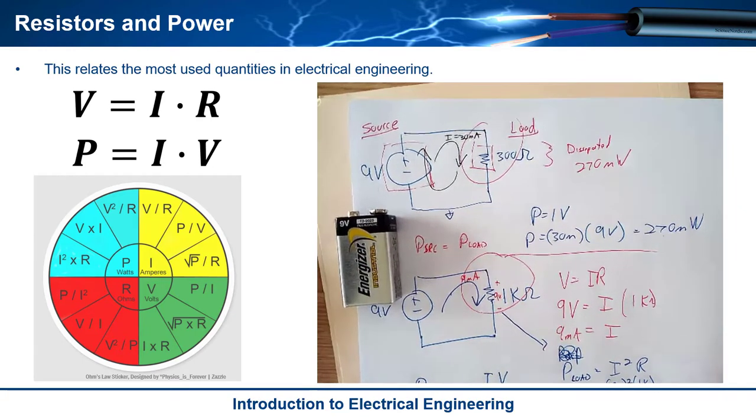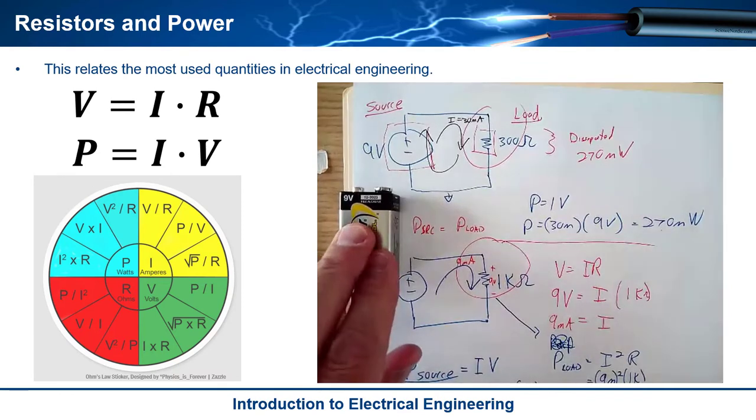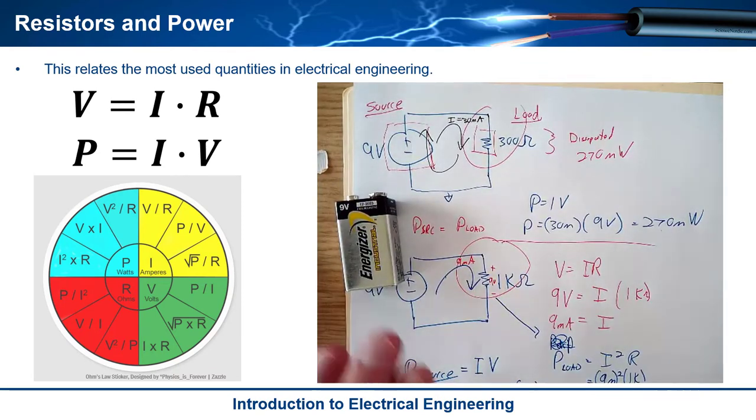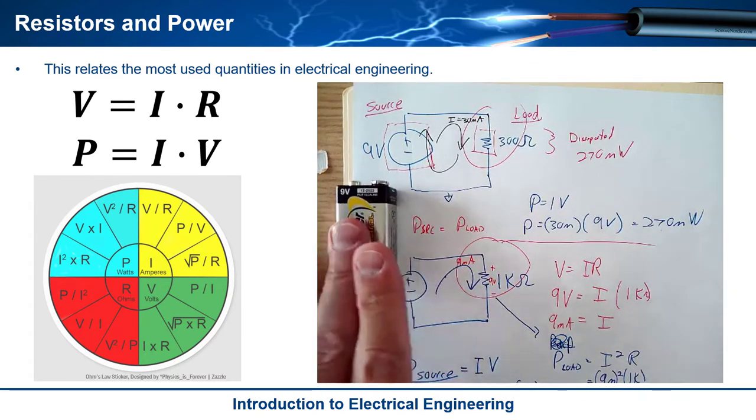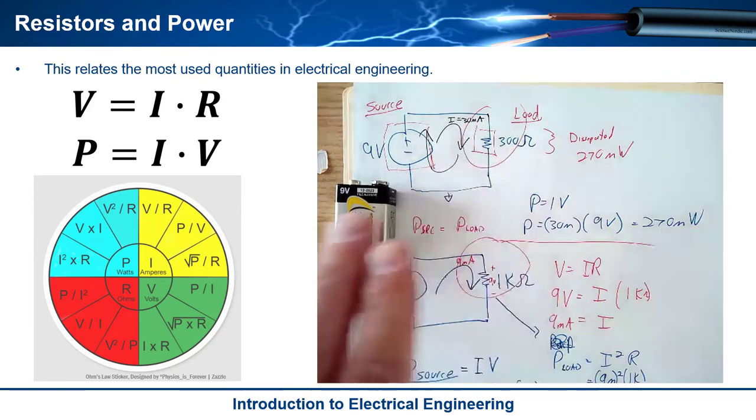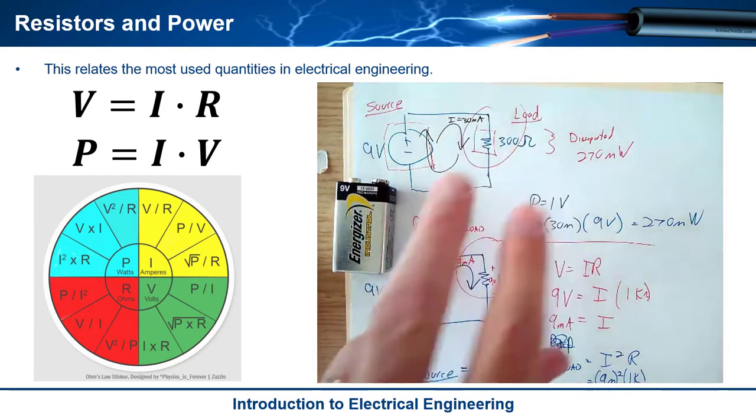Of course, you can exceed how much the source can provide. So that's part of the design consideration. You might have a consideration where you say you can't pull more than 20 milliamps out of this, and then you'd be like, oh, that one ain't going to work.